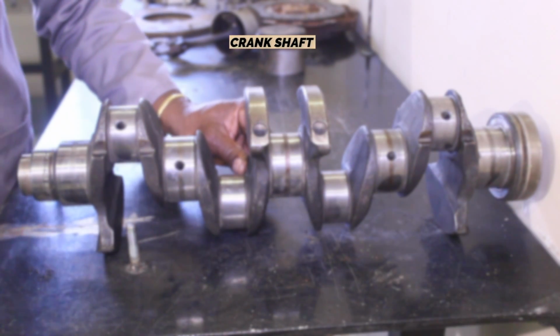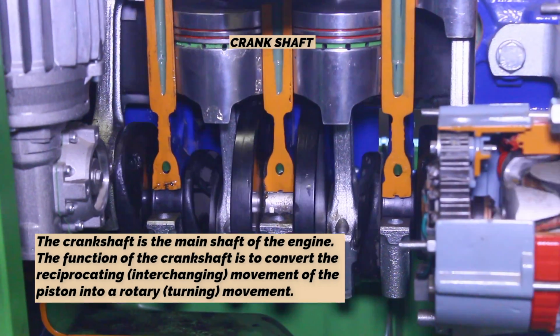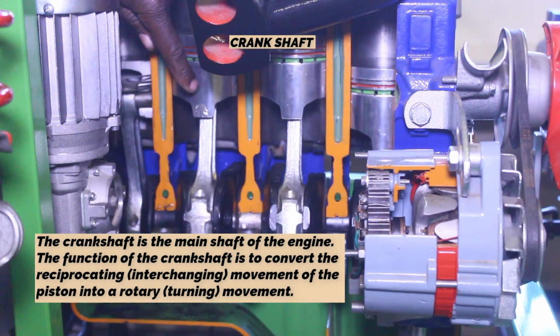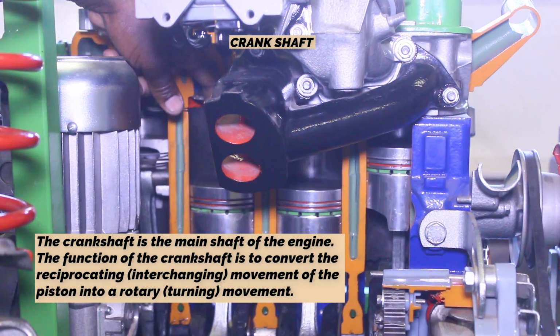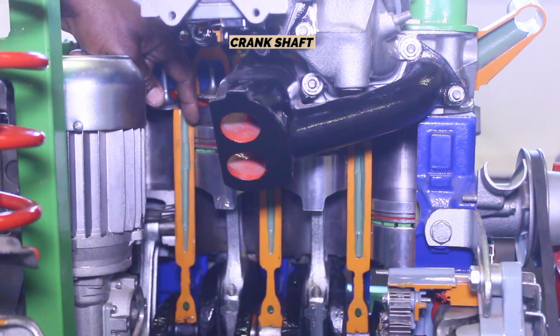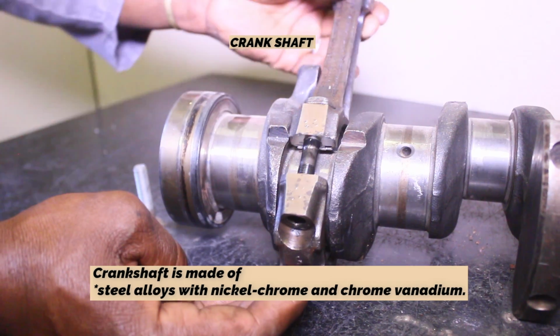Crankshaft. The crankshaft is the main shaft of the engine. The function of the crankshaft is to convert the reciprocating, interchanging movement of the piston into a rotary or turning movement. Crankshaft is made of steel alloys with nickel chrome and chrome vanadium.